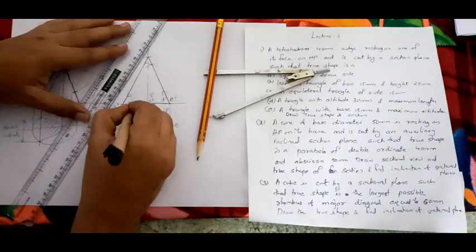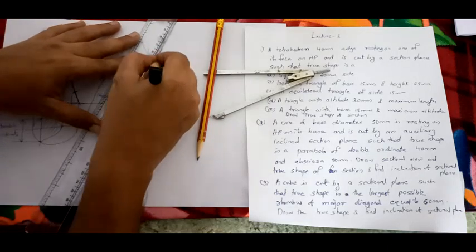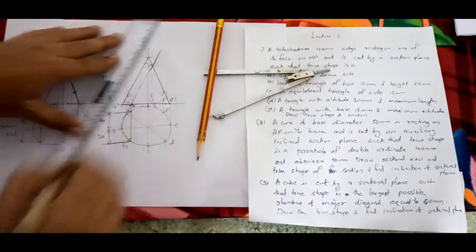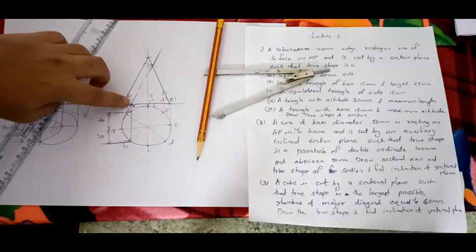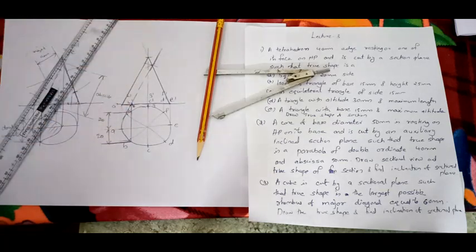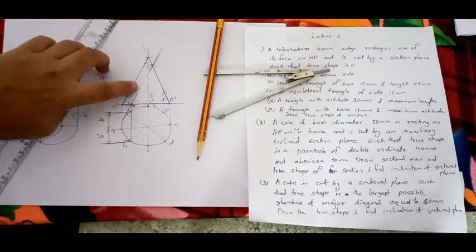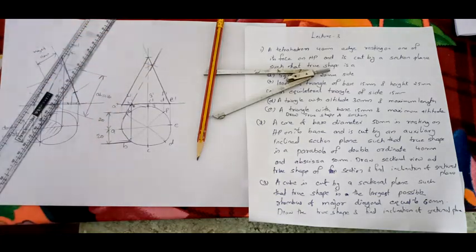And here the section plane you have already previously obtained, right? So passing through this point, draw this section plane also. From this point you have already found this point, right? From this point join the previous point obtained from projecting here, and this will be your section line. These two lines should be parallel. If they are not parallel, your answer may be wrong.